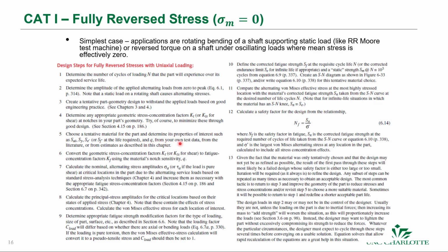And we put all this together or do estimates. And this is really the magic of engineering here. It's going from these requirements into that embodied design. Okay, and then we correct our stress concentration factors for fatigue using the material's notch sensitivity and the Neuber constant for that material, which we just talked about today.